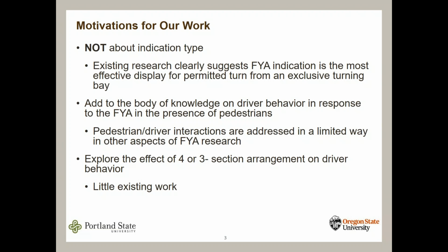But we really wanted to take a dive into looking at how the flashing yellow arrow might affect the driver's behavior in the presence of pedestrians. This is a little bit down in the weeds of traffic engineering, but we wanted to look at the effect of whether you could have a 4 or a 3 section head. Both of those topics haven't been explored as much in the research prior to our work.